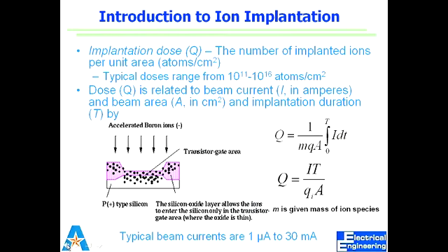Exactly how do we do that? Let's be a little precise. You etch it. Okay. Let's take a step even further back. What would be the first step we would want to do? You define it. We would define the area we want to etch, right? So if it's silicon dioxide, simple photoresist is going to give us that area where we can do that.